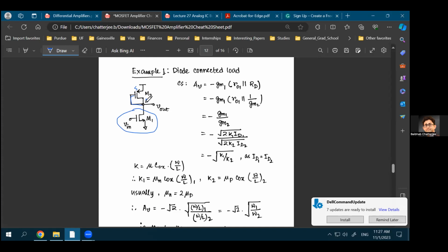And you know that for a diode connected MOSFET, looking into the drain of the MOSFET, you'll see 1/Gm. That's the resistance. Instead of having a resistance of RD connected at the drain of this M1 transistor, you're connecting a resistance of 1/Gm that comes from the M2 transistor. So the analysis will still be same. You do not need to consider two different transistors. You can just divide and conquer. So that's something you always need to do for any kind of circuit that you see.